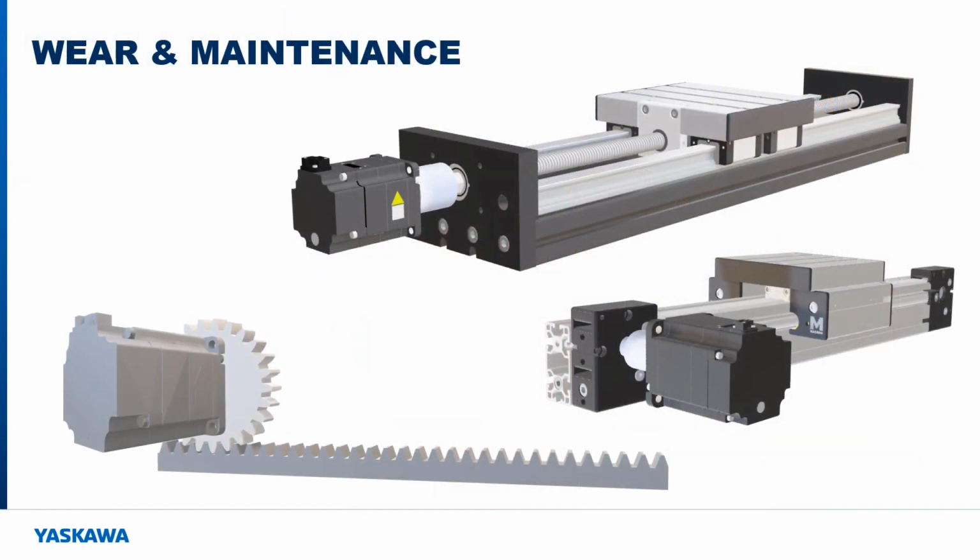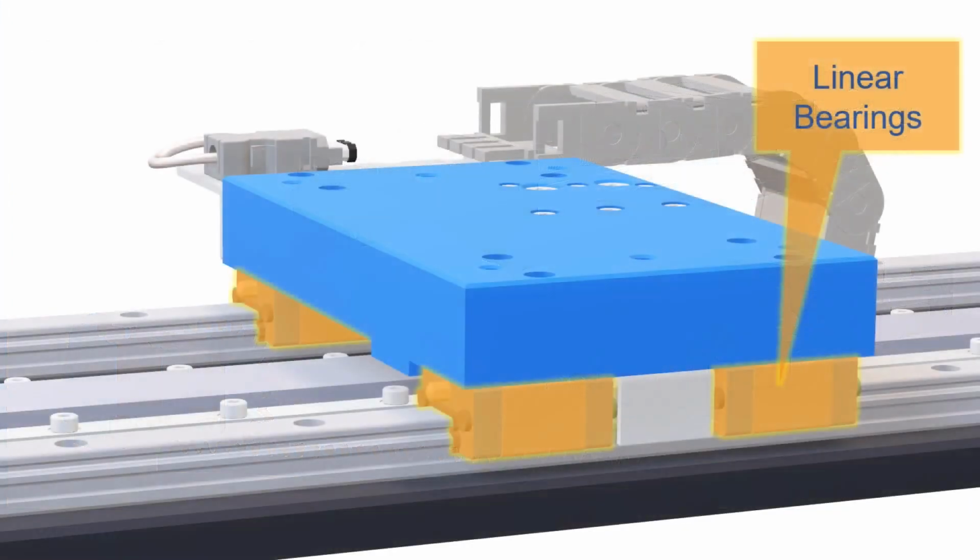From day one, the performance of these mechanical systems begins to decline. The backlash and stiffness get a little worse every day. Therefore, expect positioning time, accuracy, repeatability to continually degrade as time goes on. The linear motor bearings do eventually wear out, but quite gracefully by comparison.